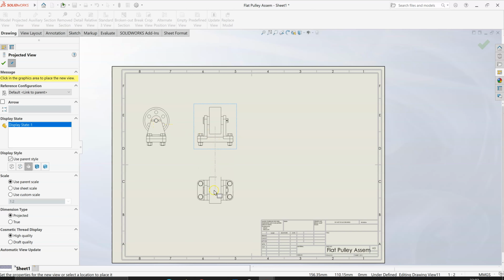I'll also project a plan view, which will be shown down below, so the view from above displayed down below here. That's your standard plan, elevation and end view in the first angle projection scheme. Now you can also project isometric views off like this, but I'm not going to do that as a projection. I'm going to do it as a separate pictorial view, let's say.